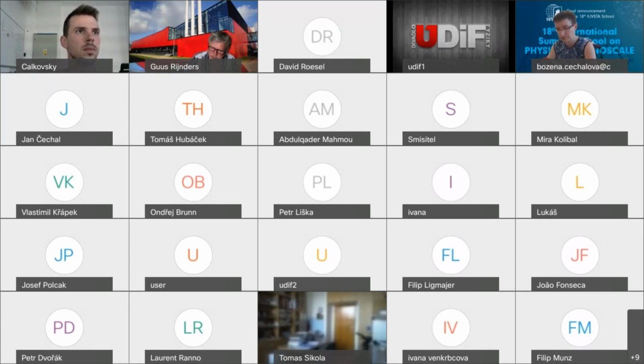Yes, we can tilt, because you can play tricks with the electrodes, so the applied electrical field might be different at every position. But you can also play around with the geometry. Because of the clamping of the substrate, you can have different types of out-of-plane movement, and with that, you can make tilts.